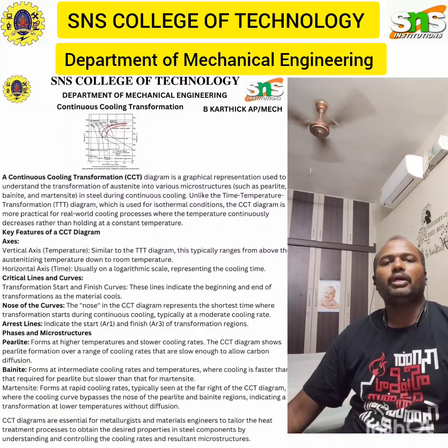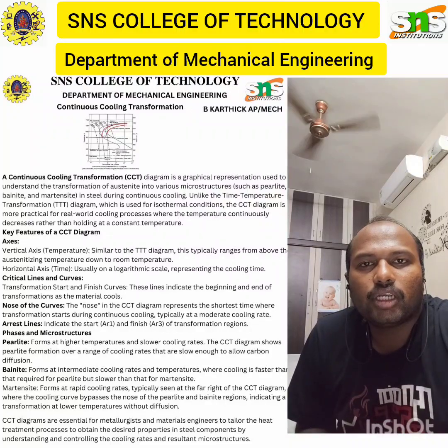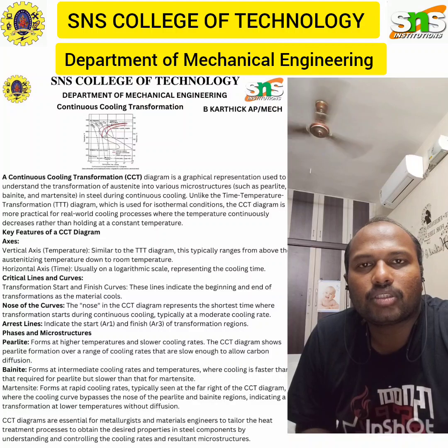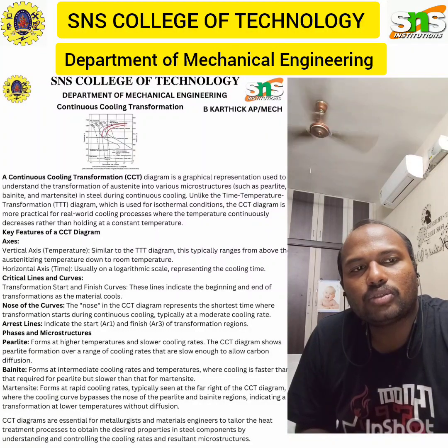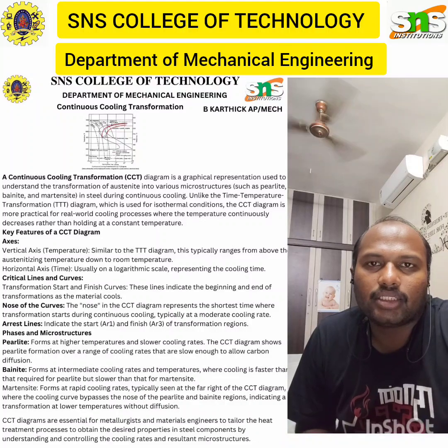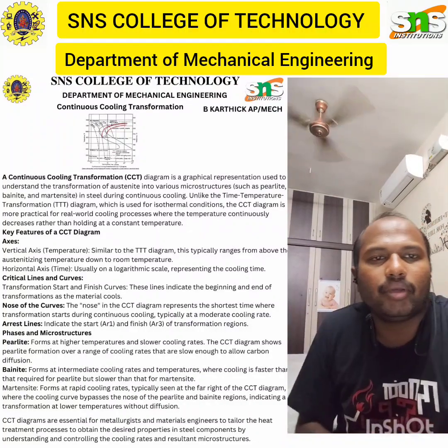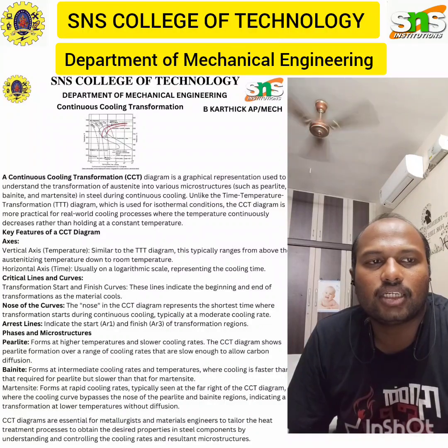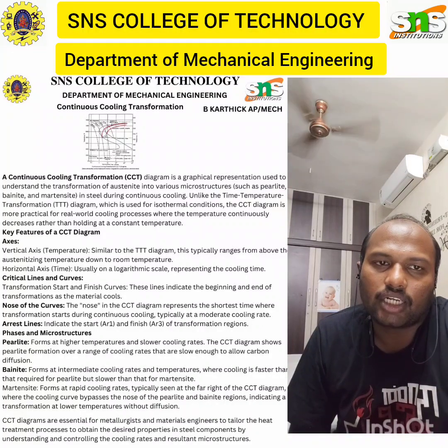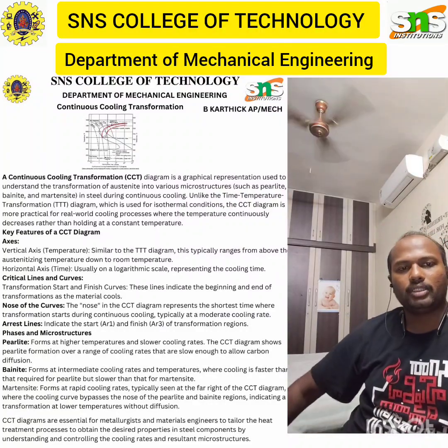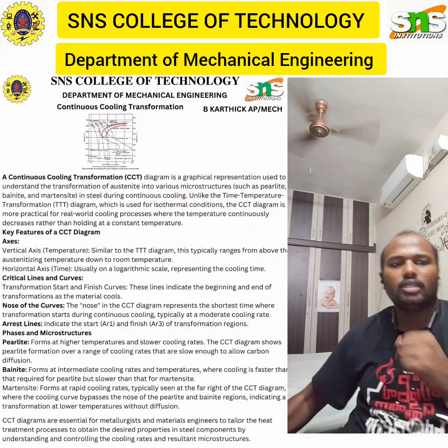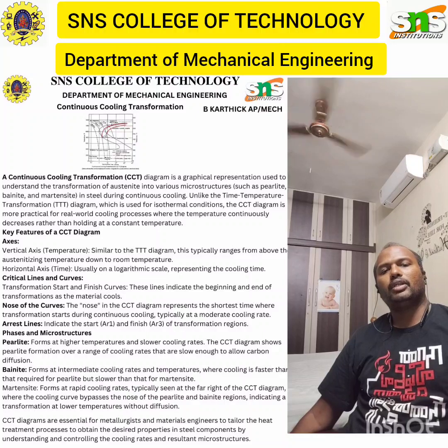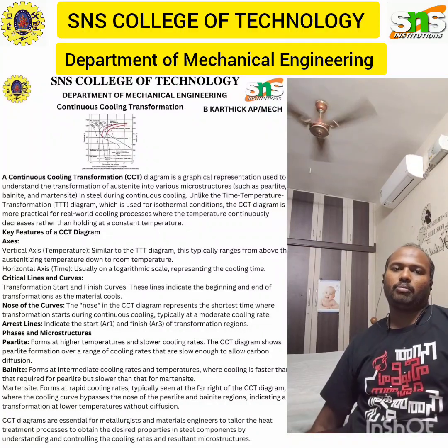So in the cooling path, for a very slow cooling, the cooling curve might pass through the pearlite region, resulting in a microstructure predominantly composed of pearlite, which provides a good balance of strength and ductility. The cooling curve could pass through the bainite region, leading to a bainite structure which offers a combination of high strength and good toughness, as a moderate cooling. On rapid cooling, which is quenching, the cooling curve bypasses the pearlite and bainite region, as I said already, resulting in martensite structure, which is very hard and brittle. The structure typically requires tempering to alter the property for practical use.